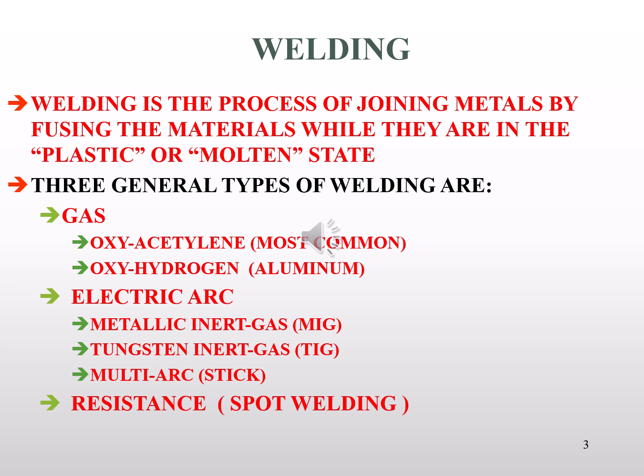The second point I'd like to make on this PowerPoint is there's a common question: what are the three types of welding? Well, the FAA recognizes these three types. Gas welding, the oldest method, electric arc welding, which is going to be all of your modern methods, and then finally resistance, known to many of us as spot welding. However, spot welding is generally used in a manufacturing environment, not so much in repair, but there's your answer to that question.